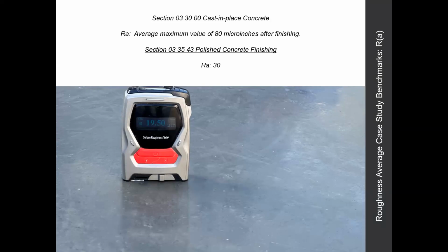And to illuminate a little bit on working with the contractors, they were already at about a 30 microinch level of the surface, and they introduced a tool that brought them, excuse my French, damn near close to 80 microinches. So they were literally going back in time on the schedule by making the surface way too rough. The other thing they were doing, of course, is compromising the integrity of the crown.